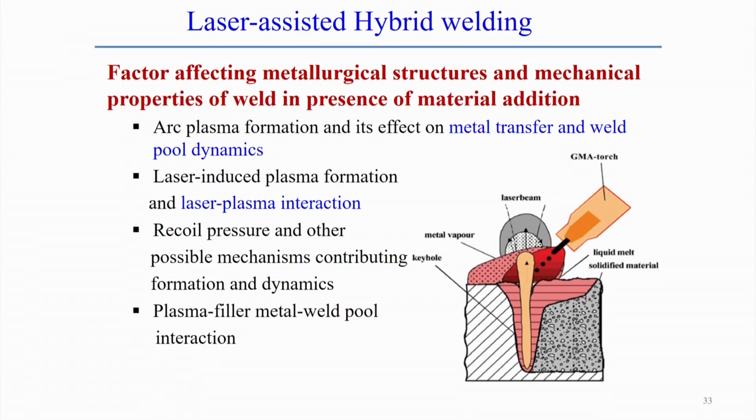First point is the formation of plasma, and that plasma formation actually affects the metal transfer phenomena, and ultimately it affects the weld pool dynamics. Second point is that laser induced plasma formation and the laser plasma interaction become more complex in this case. So, that interaction actually helps the absorption of the energy during the welding processes.